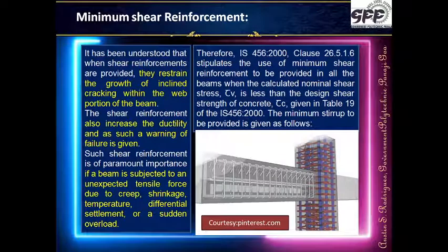There is another clause which has been given about minimum shear reinforcement. Now we know that in a beam, when shear reinforcement is provided, this shear reinforcement restrains the growth of inclined cracks, prevents or does not allow them to propagate more. It controls the growth of inclined cracks within the web portion of the beam. Now the shear reinforcement also provides ductility, and as such it gives us a warning,